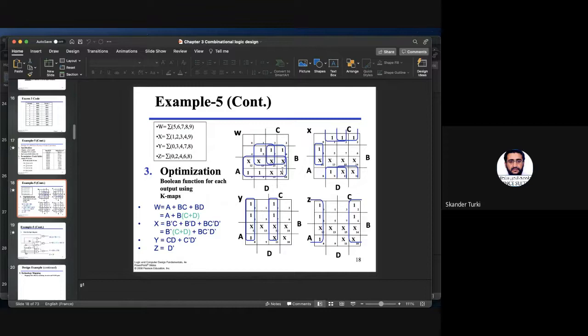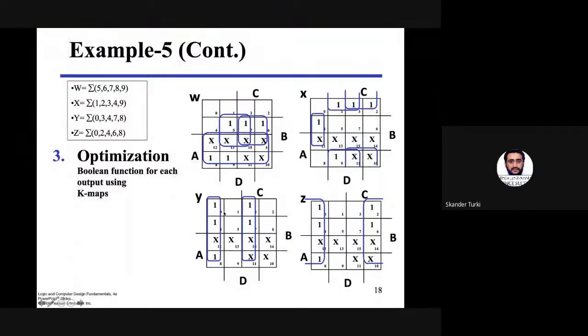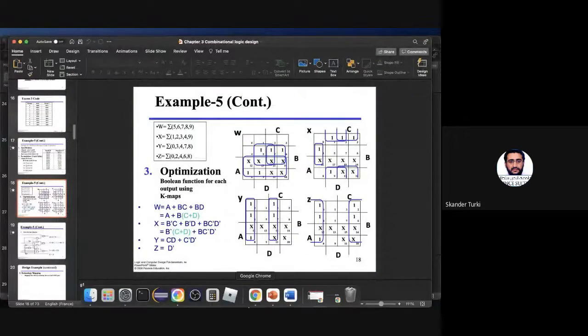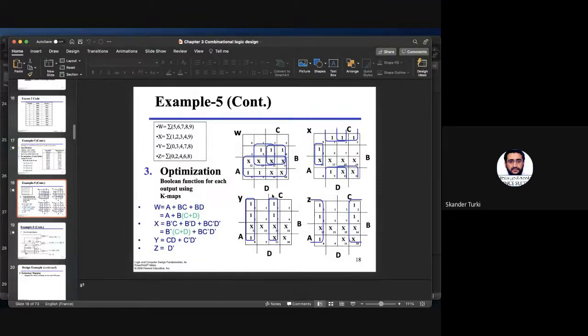The thing you don't understand is why they are don't cares, or how we deal with them when we group. You have to deal with them as jokers. Like here, for example, if they allow you to have a bigger group you take them, but you don't have to cover them all. Like here, you don't need them, they are not useful, you leave them.